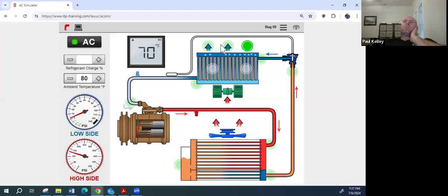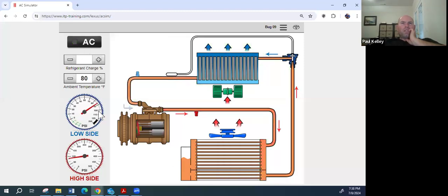Oh, sometimes. Now it's blowing 70. 78, 79. No, that sucks. That AC's an op. Now, what do you want to do? Just think about it, consider it, weigh it out, go over the possibilities. How about we check the static? We got about 88 PSI on an 80-degree day. What do you think? Is that under or overcharged?